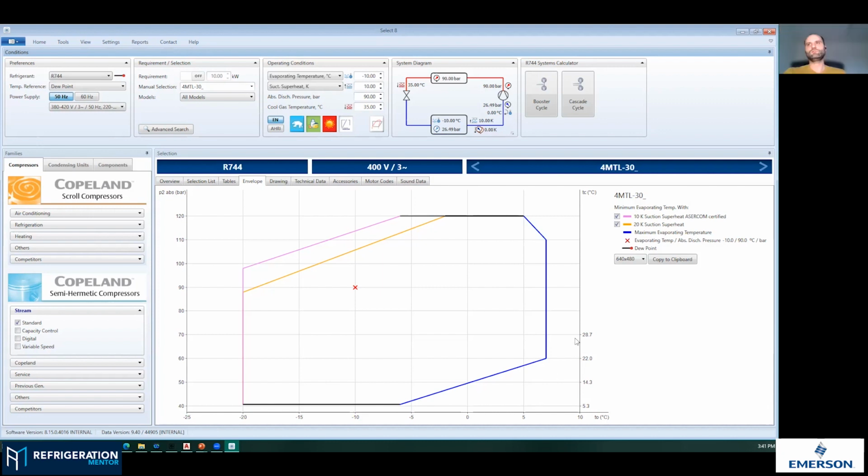Not only the screens? If you go high with the discharge pressure, then yes, because it can lead either to the motor tripping because of too big amps, or as you said, there are very big loads on the components because of this too big input power. But actually, I would say that the component sizing is somehow imbalanced usually with the maximum motor power.